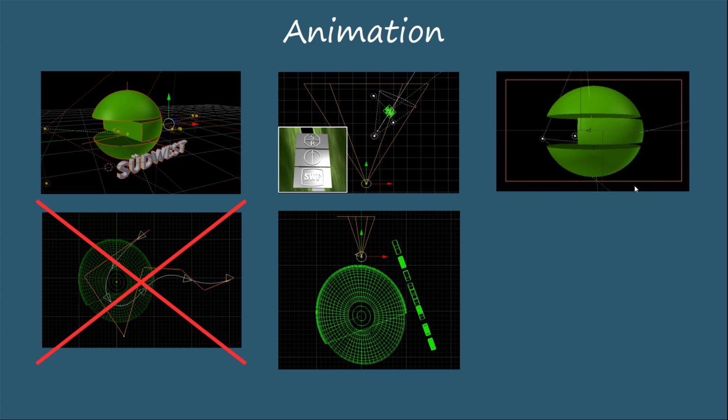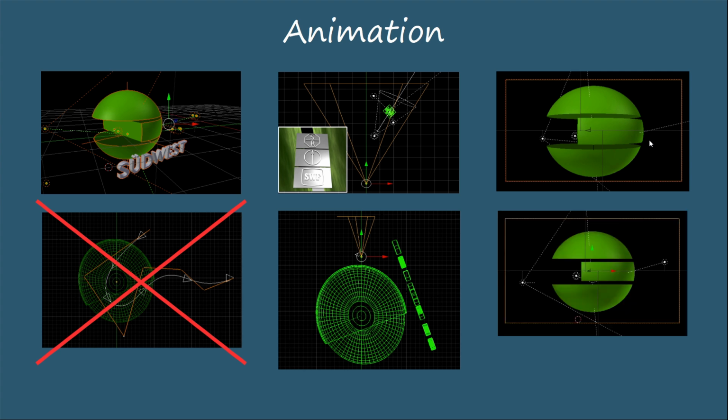Finally, what you have probably noticed in the end, you will see this 3D logo here in the end, but it doesn't look exactly like this logo here. So it's not really a perspective view on the logo, but it's more like an orthographic view on the logo. So it almost looks like this. To achieve this effect, I basically changed the focal length of the camera.